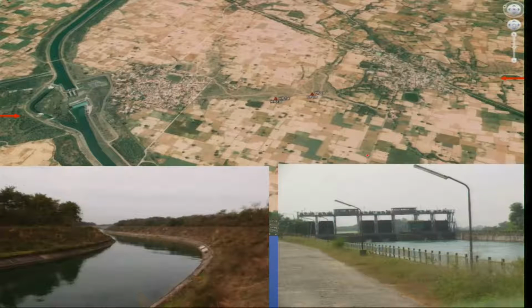So, we have the fault which is running here. There is a Google picture which shows this, and then they have constructed this. Now what hazard will there be? If an earthquake occurs, this area will definitely break, and there will be surface rupture. This surface rupture will definitely damage the structures sitting on the fault scarp, and there will be local flooding which will be extremely dangerous.